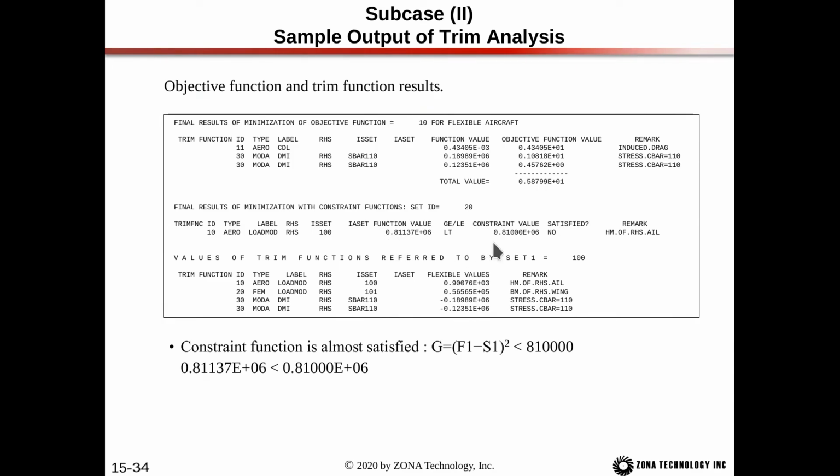So my recommendation is if you have a hard constraint value, just multiply it by about 95% and then use that as your input constraint value in ZEUS, and then that will make sure that you satisfy your actual constraint. So this is just due to the solver method in ZEUS. It is allowed to bust the constraint by just a little bit.